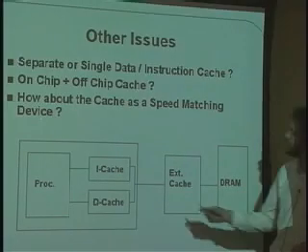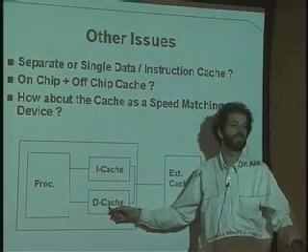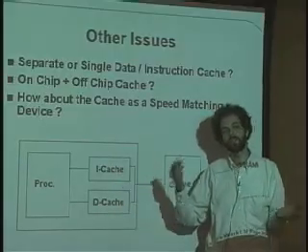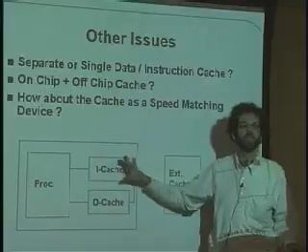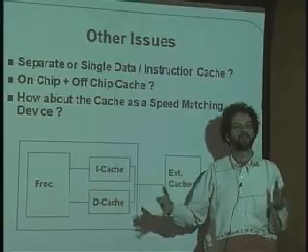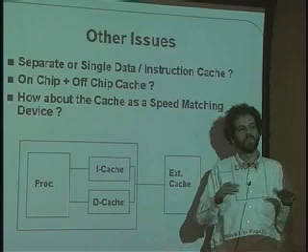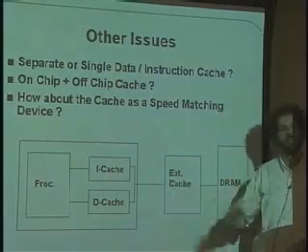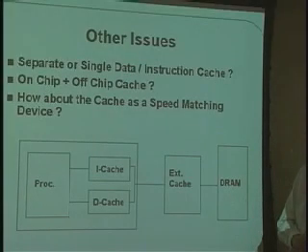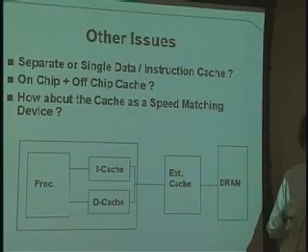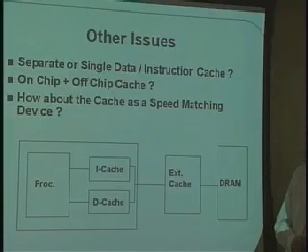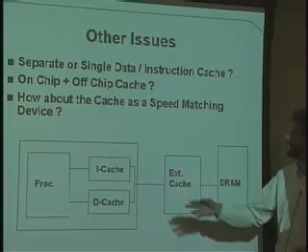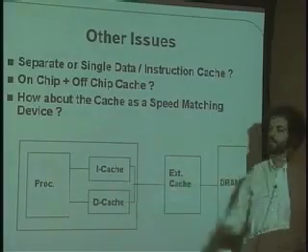Unless for some reason some programs are more data intensive than others. So sometimes you find that this cache is being used more than this cache, or this cache is being used more than that cache. And if that's ever true to a great extent, then usually it would have been better to just have one of them where, regardless of which is being used more, the total is available to both. But the reason you want them separate is what? So that you minimize the collisions between the two sides, right? That's absolutely right. And so this is one of these higher order architecture issues, but you see people talk both ways as to whether they should be separate or the same.